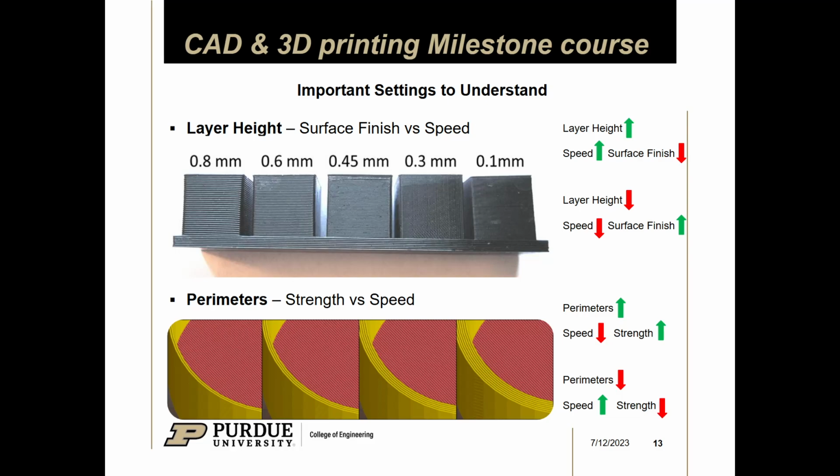And the layer height basically tells you how coarse or how fine to slice that model, right? So the more times it slices it, the more accurate your 3D printed model will be to whatever design you had before, but the longer it'll take, right? There's more layers for you to print, and each layer takes a certain amount of time. So if you add more layers, it'll typically come at a reduction in speed just because it takes longer, but you'll get more details, right?